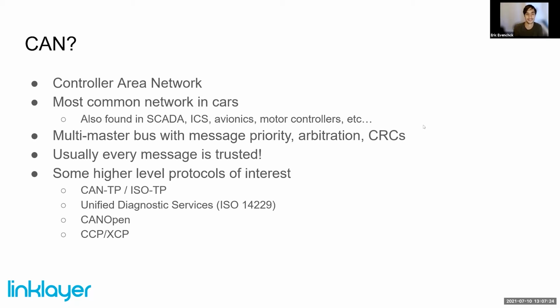On top of that, CANTP and ISOTP, we'll see things like Unified Diagnostic Services, which is the ISO 14229 standard. This is the protocol that whenever you bring your car into a dealership and they plug in, there's a very limited subset of what are called the OBD functionality, onboard diagnostics. This is a standardized format that you can buy those off-the-shelf tools for. The version of OBD2 that's out there right now, you'll find in every car made after about 1996. So that's a very basic interaction.